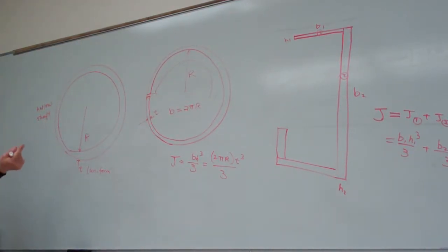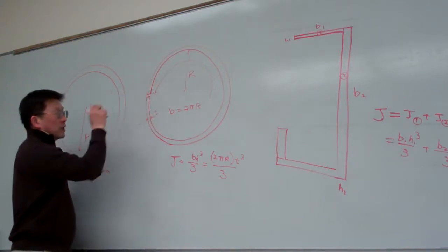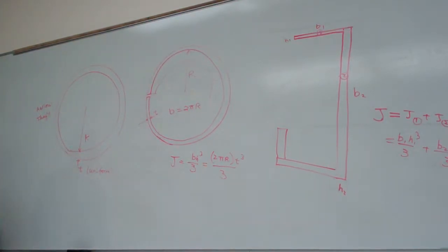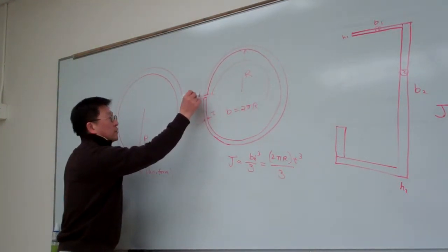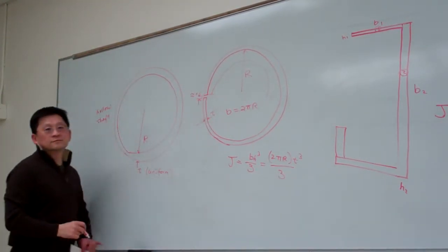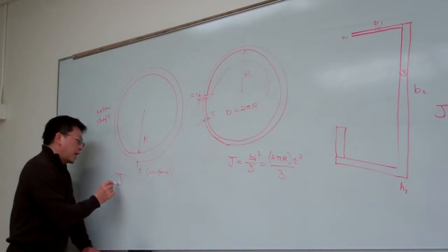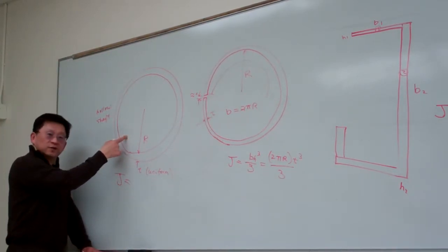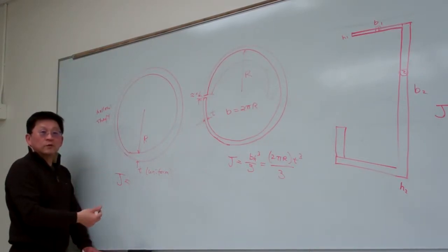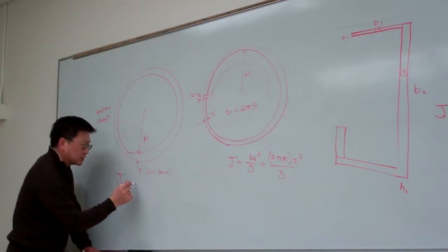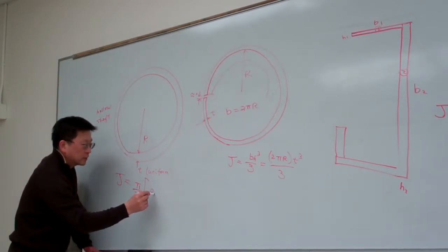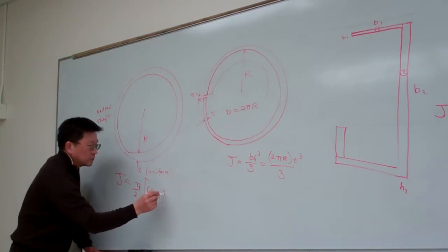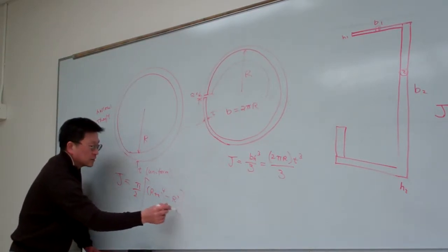This shaft is different from this because here we have a small cut, and let me say this space is almost 0. Are you able to calculate the torsional constant for this? That simply is our polar moment of inertia, right? So that one is pi over 2, if you remember, outer radius to the fourth minus the inner radius to the fourth.